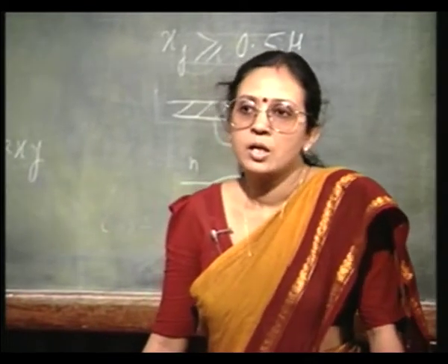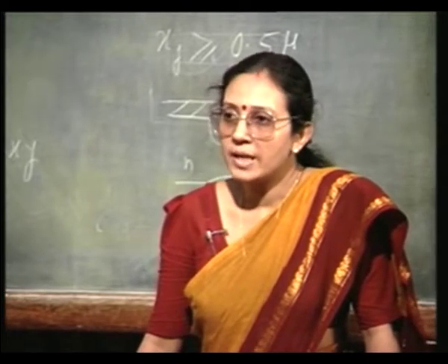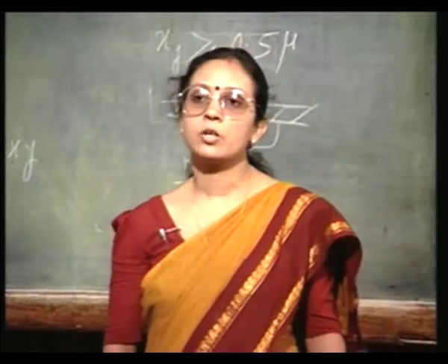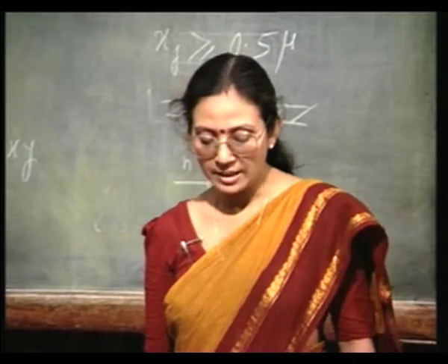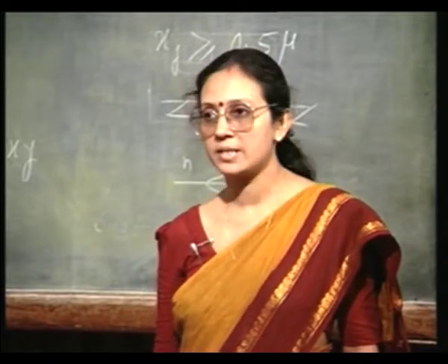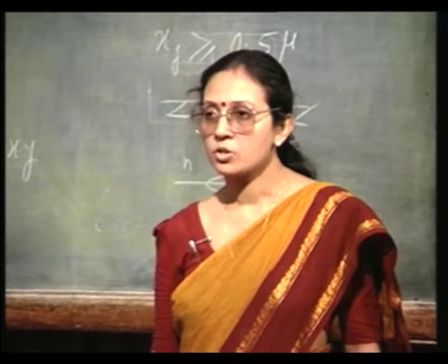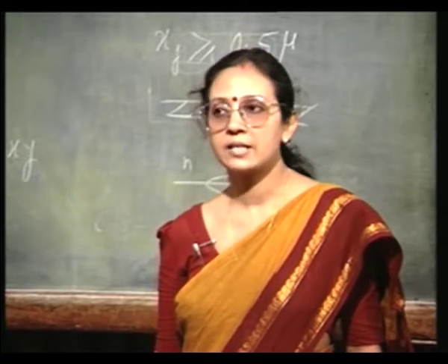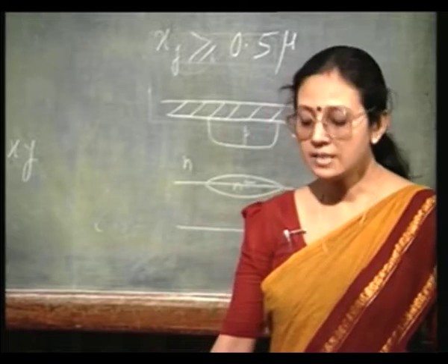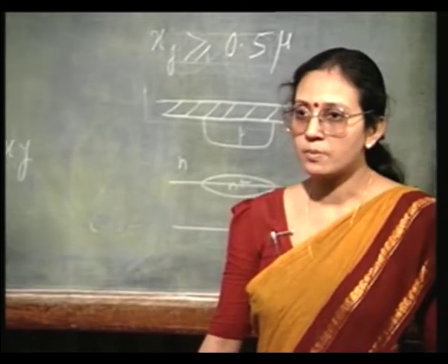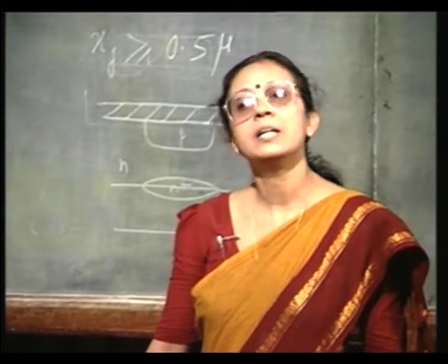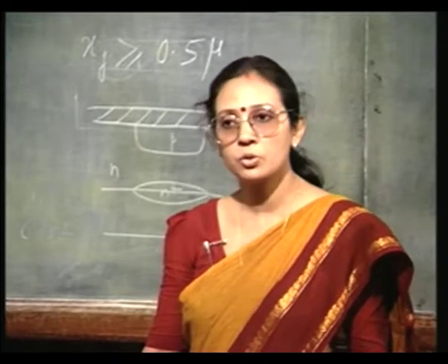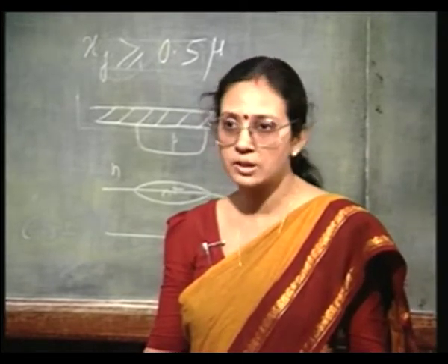First of all, the beta of a transistor depends very much on the total amount of dopants, the total amount of charge placed in the active base region. That is called the Gummel number, and it must be low for realizing very high beta. So, if you want a high gain transistor, you must control the total amount of charge that is being put in the base.